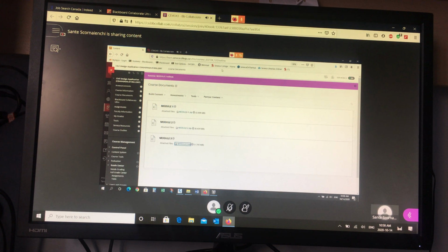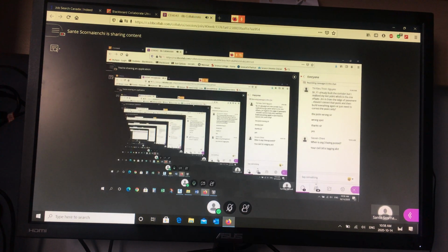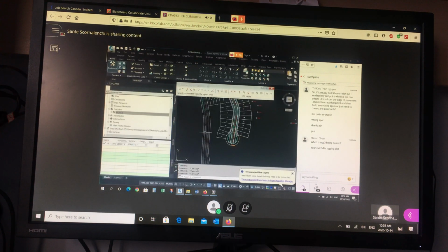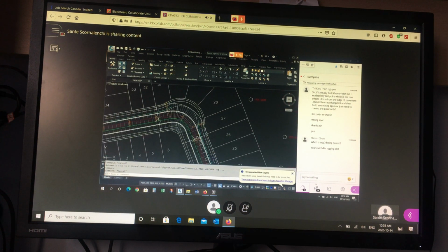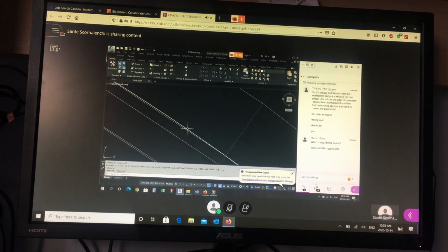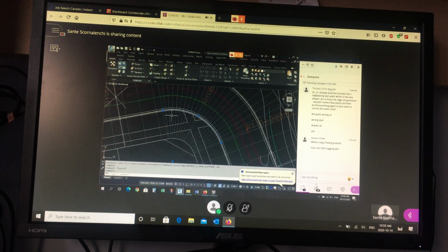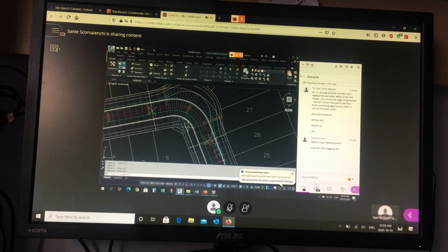So back to here. Okay. Civil 3D is lagging a lot. Trying to slow down as best as possible. Okay, so what I want to do is widen the elbow. And remember that the inside is okay. The edge of asphalt is exactly where it's supposed to be, because it doesn't widen on the inside, just on the outside.